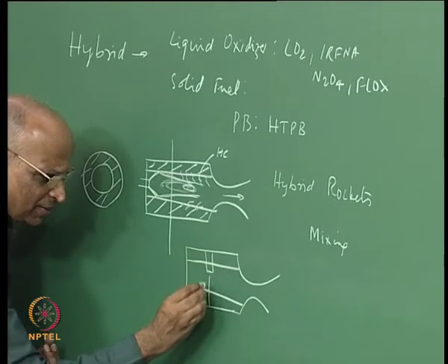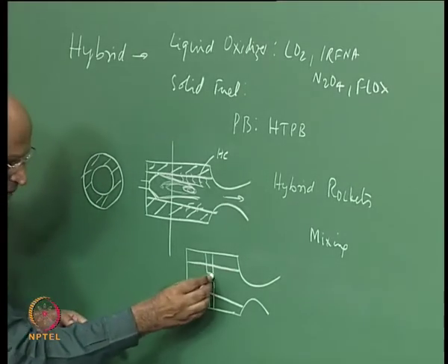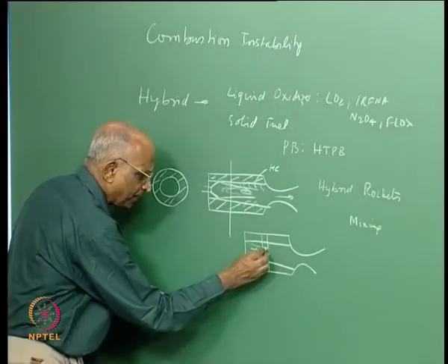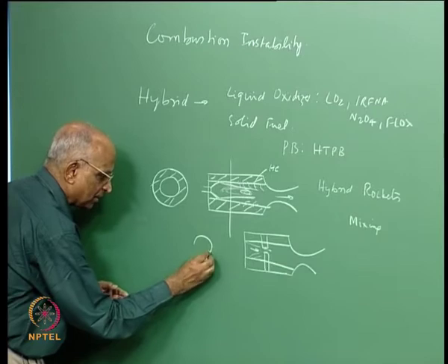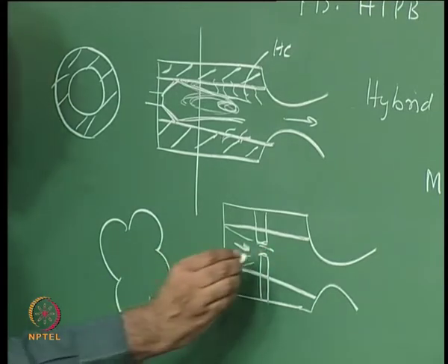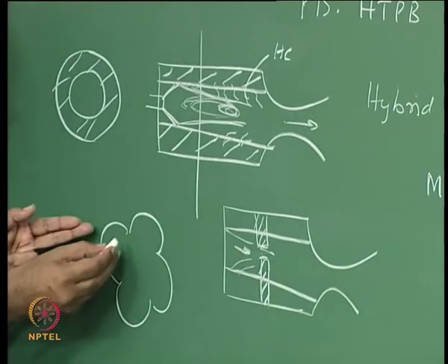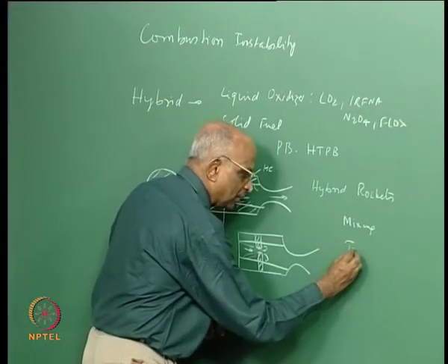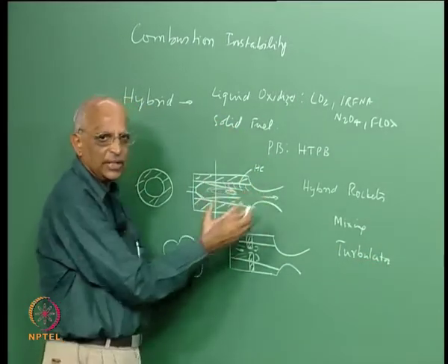What is a turbulator? It's very common in all engineering situations. Fuel is getting evaporated here, oxidizer is coming over here, and I make a constriction in the form of, let us say, a petal, something like this. I put this configuration in this hole, and this is a turbulator. When the gas flows across it, it creates eddies and helps to mix, so we need something like a turbulator normally for mixing the gases, so that combustion gets completed.